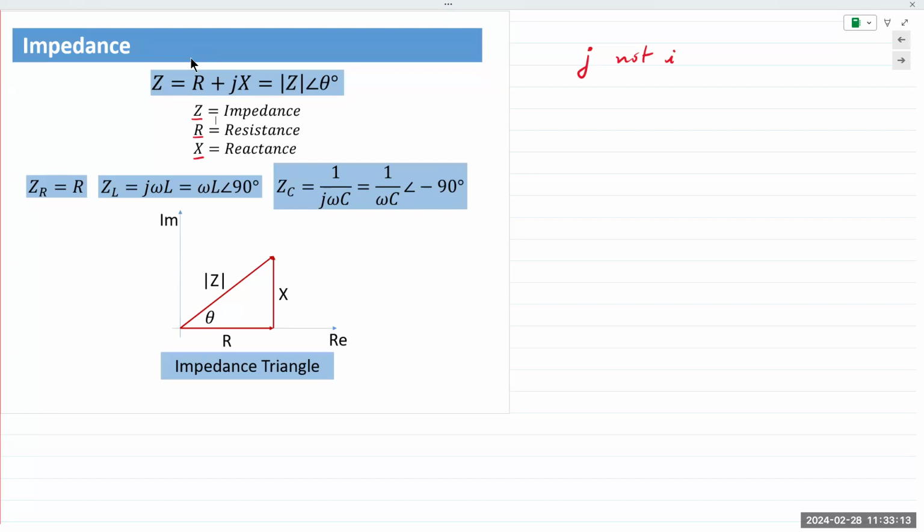And so it has reactance, it has impedance. Typical speakers are about 8 ohms or 6 ohms impedance. If you look at the spec sheet of an amplifier, at the end of the manual, it'll state it can supply, let's say, 100 watts per channel into an 8 ohm speaker impedance. That's where it comes from.